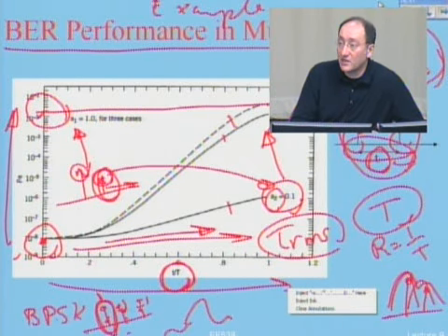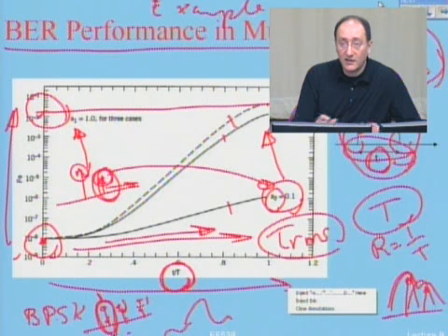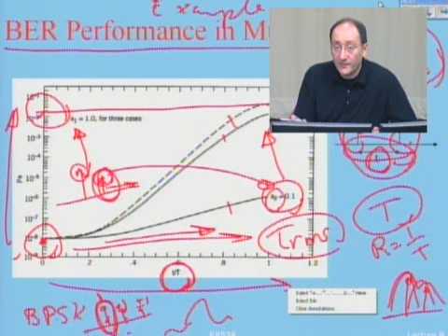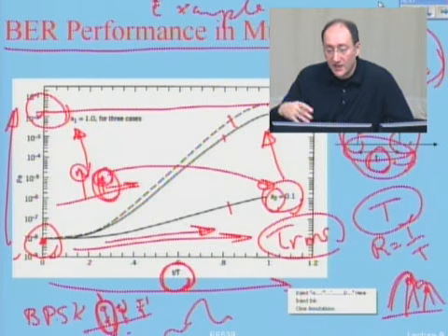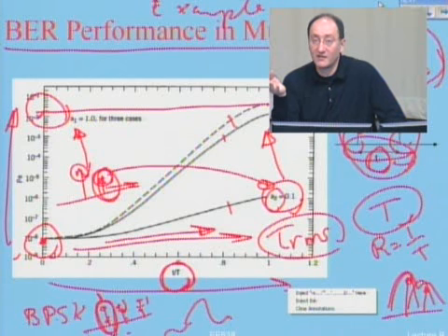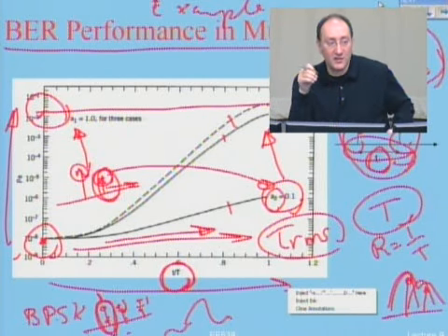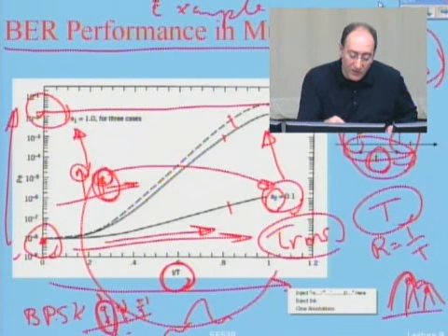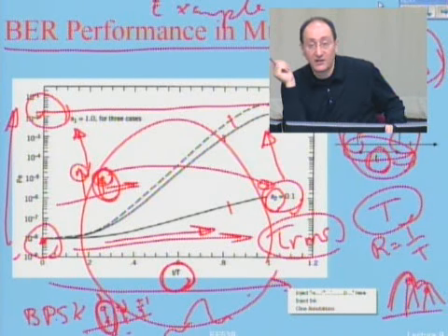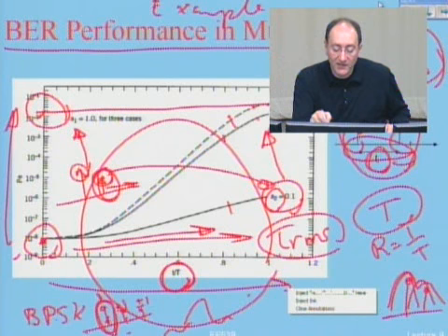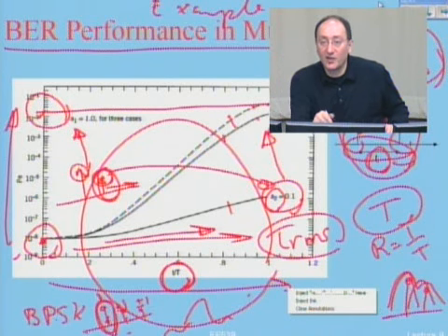So there are two sources causing errors in multipath. One is the spread of the channel. The other one is the strength of the second path. Usually we combine both of them in one parameter, which is tau RMS. And you can get similar results for that as well. Then you don't need to have 3 paths, for example, 3 different types of A.